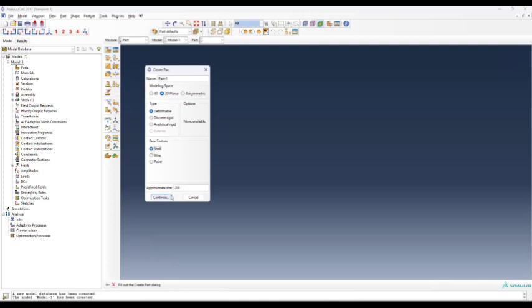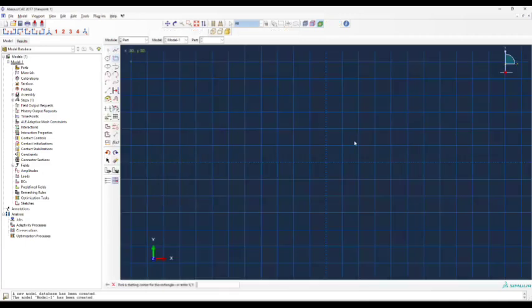So shell now means it's going to be a real part with volume, a real part as a plate, as a deformable material, not a wire anymore, which was just thin kind of truss members. Okay, so continue. I'm just going to call this plate or whatever. Continue. Okay. So now we're going to create the geometry.